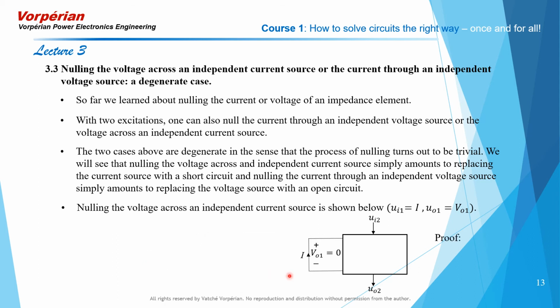The proof of this is pretty straightforward. It is the substitution theorem, and you work it backwards. If I have a circuit this way, where there's a branch, obviously the voltage across that branch is 0, and I have this excitation input 2 being applied to this circuit, there's going to be some current flow here in this branch with 0 voltage appearing between these two nodes.